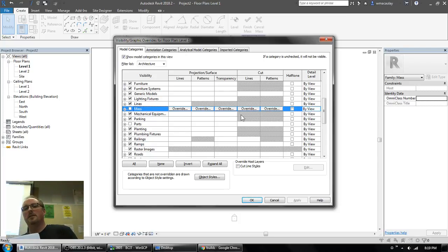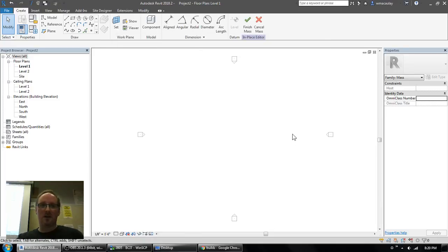The idea with massing is that it is there as a guide in the background, helping you create the form of your building. It's like a skeleton that you build on that you don't need to see. So by default, it's turned off. Now, while you are working in massing mode, Revit turns on massing, and if you go to the Massing and Site tab later, we'll see how you can turn it on by default. So here we are inside the massing system.